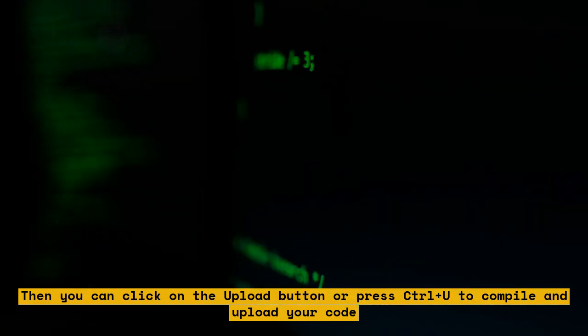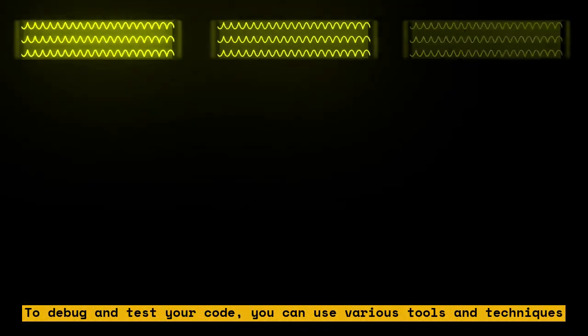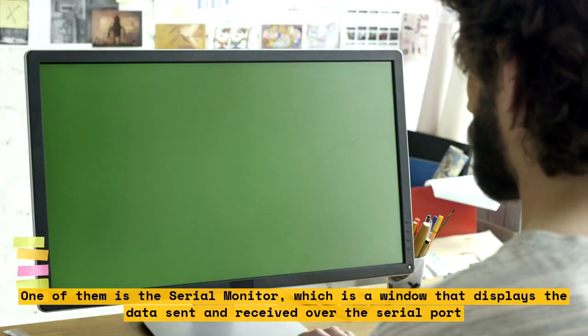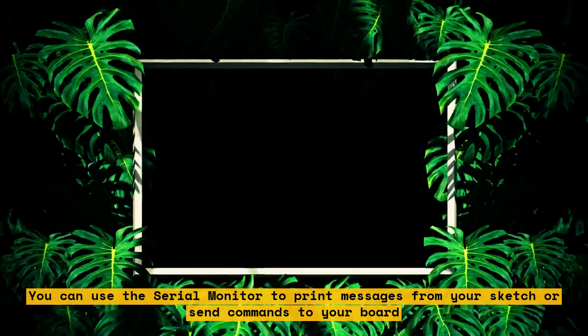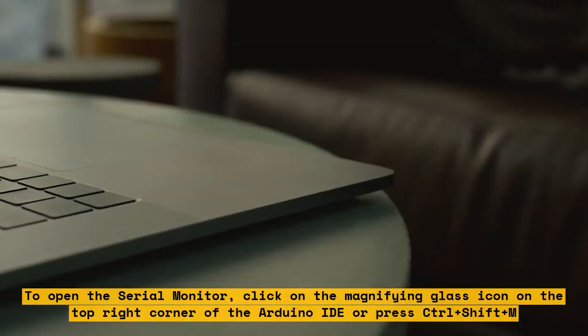To debug and test your code, you can use various tools and techniques. One of them is the serial monitor, which is a window that displays the data sent and received over the serial port. You can use the serial monitor to print messages from your sketch or send commands to your board. To open the serial monitor, click on the magnifying glass icon on the top right corner of the Arduino IDE